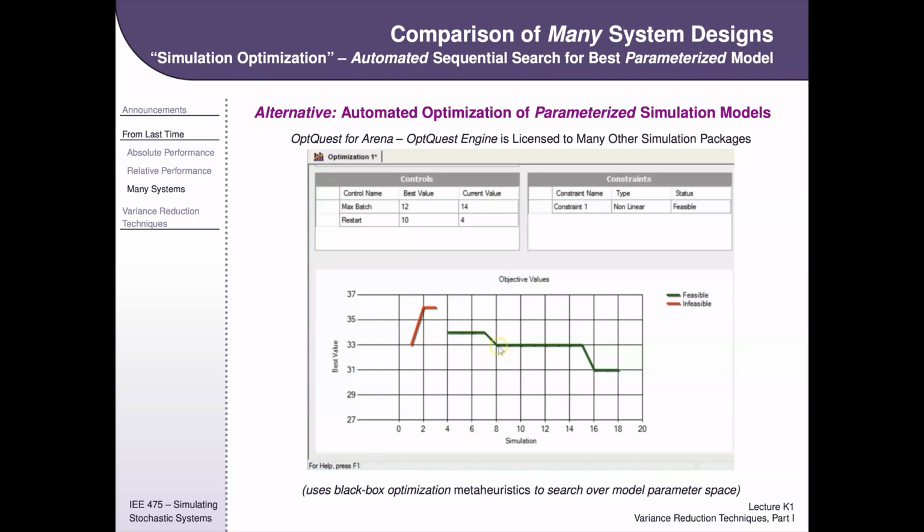And you can actually see a trajectory here. You can see that it started out with a certain configuration that was infeasible. It tried a different configuration. It was still infeasible, and it increased the performance output. Then it finally found decision variables that were feasible, so they met your constraints, and then it started minimizing them. And you can drill down into them and actually see, all right, what decision variables did you use to get here? What decision variables did you use to get here? And so on. And then it finally found the best one there.